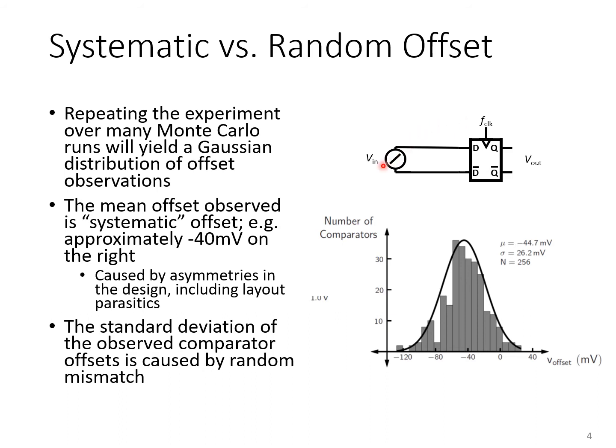And you could repeat this experiment while changing the small differential input voltage. You could do a simple sweep, or a search pattern where you look for the differential input that gives rise to the simulation result where the output looks metastable.